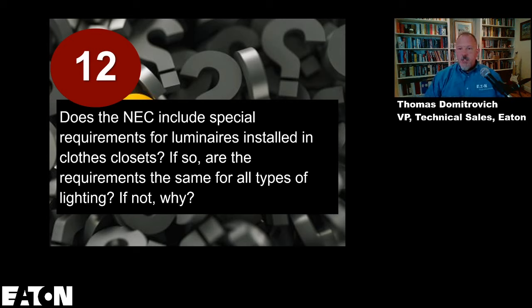In dwelling units and guest rooms or guest suites, hotels, motels. Okay, we saw that. Don Grenier is talking about also requires special construction for fixtures that use metal halide lamps. That's right, yeah, 410.130F5. That's a good point. 410.130F5. Let's take a look at that.